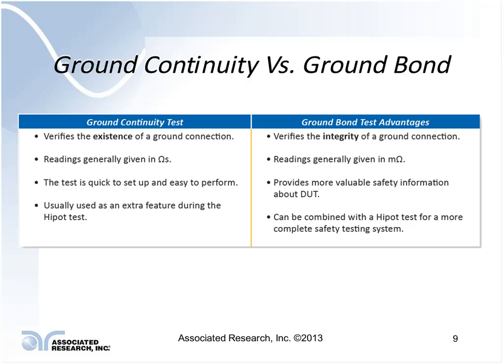So for a ground continuity test, it's a quick setup, easy to perform. It's very simple, and it's good for a production line atmosphere, especially because it is so quick.